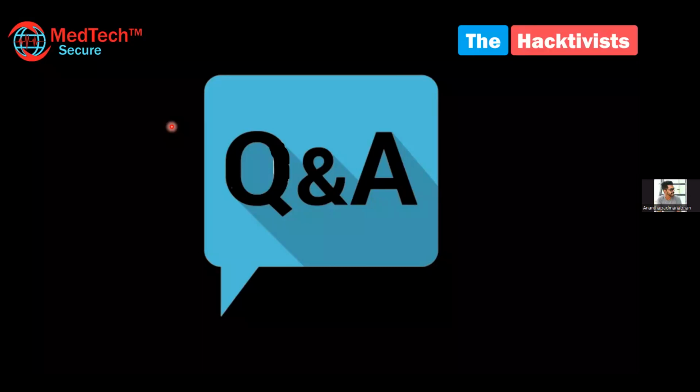Yeah, in those scenarios we can rely on open source tools like JTAGulator, just for finding out, if you have an understanding of what kind of chipset is being used, what each of those points is used for. Suppose it is a 32-bit chipset, you can connect those points using this JTAGulator device, and it also has a UI which will tell you what that particular pinout is. Even if it is not known to you, suppose the pinout has a different name, you can still try to research further regarding that.